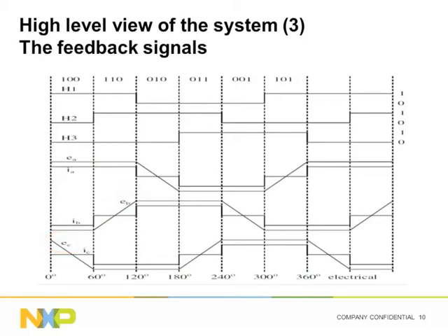By evaluating the edges of the signals, we can determine in which sector of a full 360-degree rotation the motor is actually in. This information is used to decide which of the 6 phases need to be driven at any time, since the activation of the switches depends on the position of the motor within each 60-degree sector. The 3 signals generated by the sensors are going to be used as inputs for our SCT configuration.